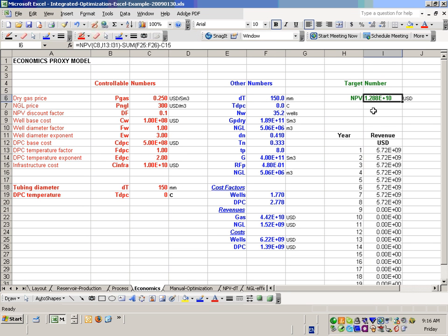And it changes through a chain of integrated calculations, going from the reservoir, okay, because at the end of the plateau, you're producing so much gas out of the reservoir. The reservoir at the end of the plateau has a certain reservoir pressure. The rate calculation says that with that pressure and the minimum tubing pressure, because you have the minimum tubing pressure at the end of plateau, you calculate the well rate at the end of plateau, right? From the rate equation. Average pressure, PC, minimum tubing pressure.